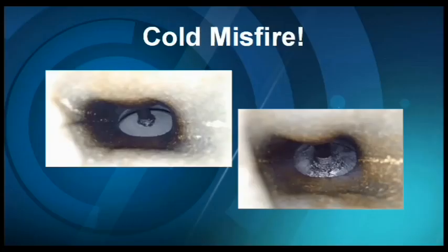From looking at the intake manifold, it looks like from oil residue that we want to inspect with our bore scope and see if we have any carbon buildup on the valves and how we're going to address it. We did an inspection at the throttle body and we noticed there was a lot of oil residue. So we decided to dig a little deeper and break out the bore scope and start looking for carbon buildup in the intake manifold runners and behind the intake valves.